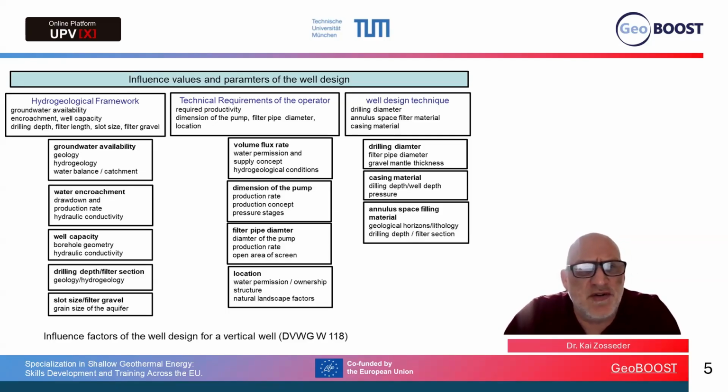And the geology, of course, also leads to your filter length and your drilling depths and so on. So you have to interpret a lot of geology and know about the rocks in the underground so that you design your well in the right way.